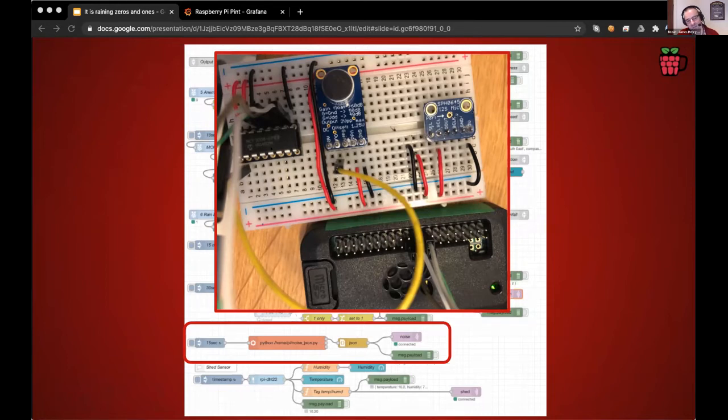Obviously, the A/T chip here is looking for 0 to 3 volts. In audio terms, a really good strong audio signal is just shy of 1 volt, so that's not going to quite work. Yes, I could get involved with some kind of gain stage along this yellow bit of wire here, but I messed about with that, and I've got a bunch of other proper mic preamps and all that kind of jazz. Bonding all that together just basically brought the noise floor up. So I was like, actually, this isn't going to quite work.